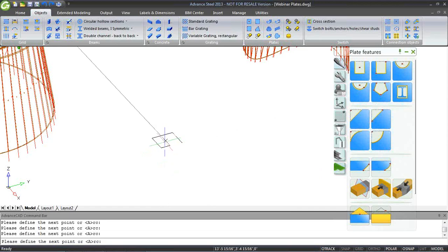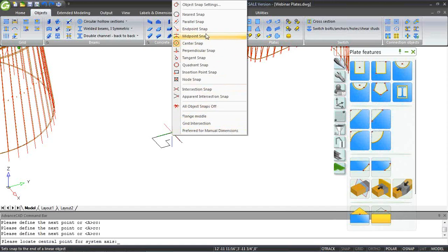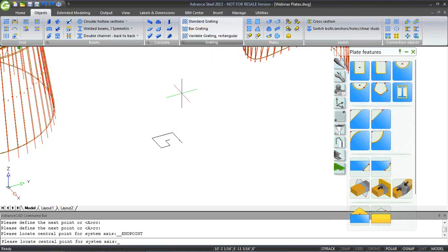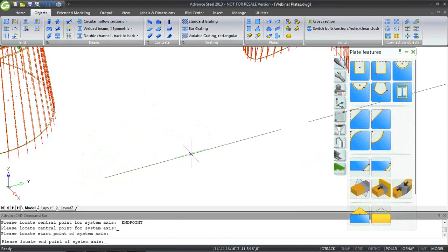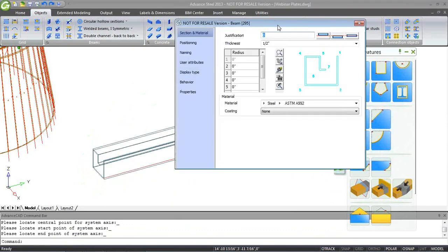And this type of work can be very useful for light gauge steel and creating lintels, gutters, so everything that's created from plates. And so I'm just defining the outer contour of what I want, and now specifying a working point, I'll be able to insert this beam in.